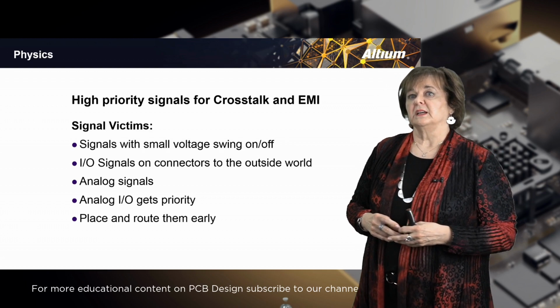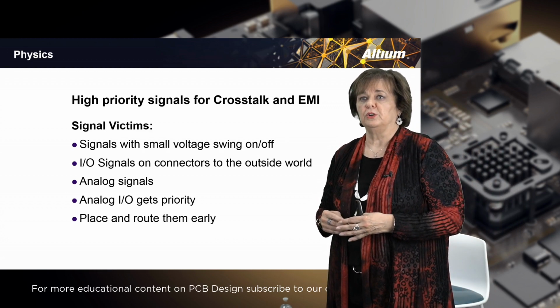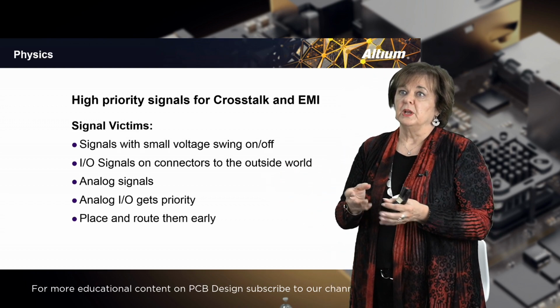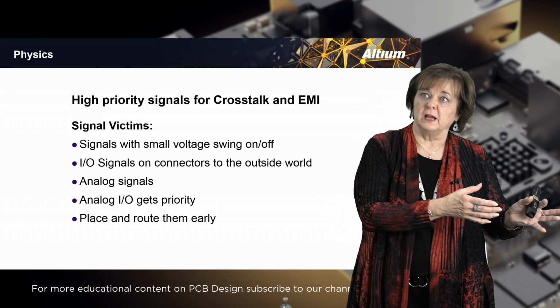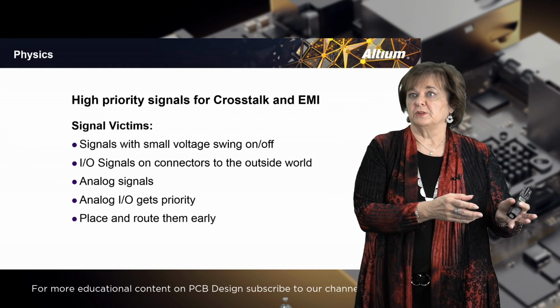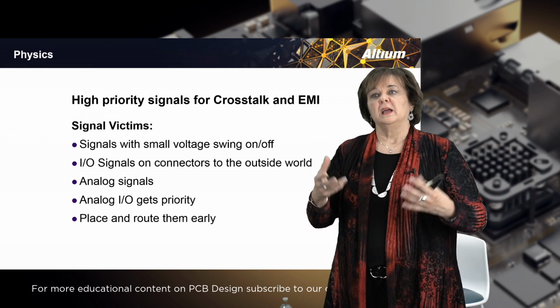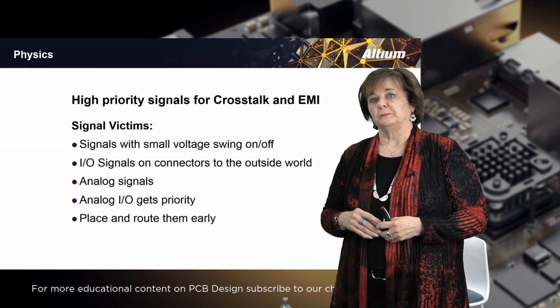I/O signals on the connectors to the outside world are a huge priority because anything that goes into the outside world from the board can create an antenna outside the board. For example, if it goes out through a cable, that cable is now a long piece of a dipole antenna, and it can cause real problems doing so.